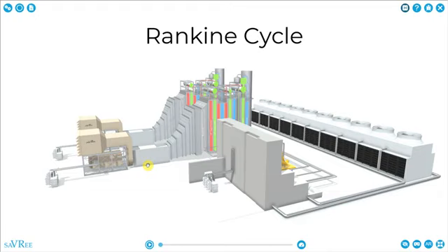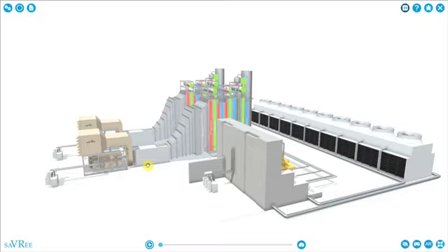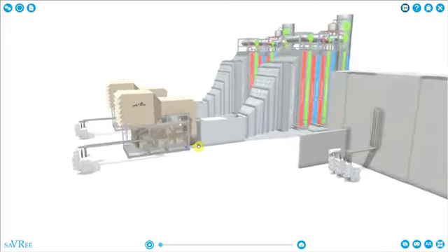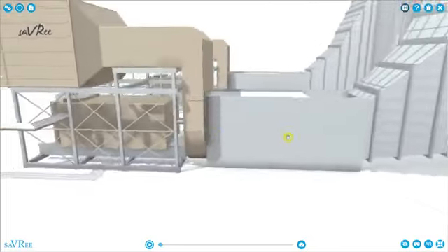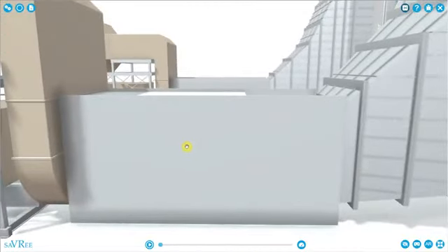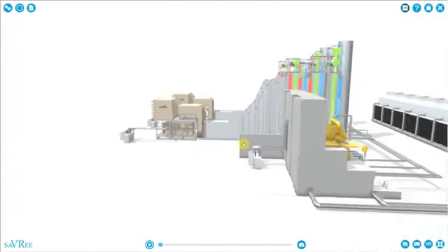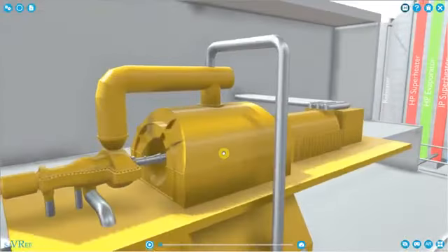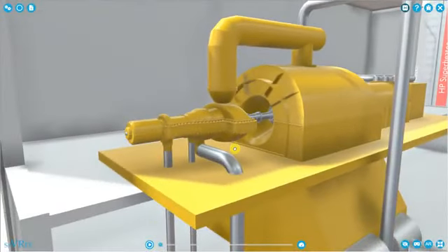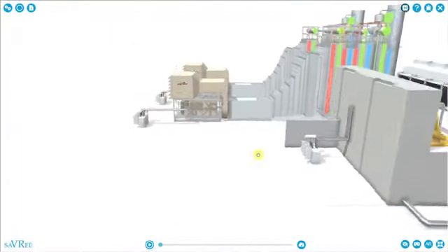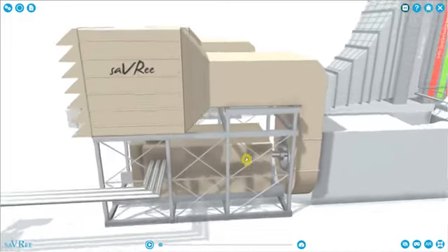In engineering, you'll also see the Otto thermodynamic cycle and the diesel thermodynamic cycle. They're all just describing different types of thermodynamic process. Because we're using a gas turbine that is housed within this box here, and the steam turbine that's housed over here, within one type of power plant, we're essentially using a Brayton cycle and the Rankine cycle together, and that's why we call this type of power plant a combined cycle power plant. Very briefly, I'll explain to you how it works.